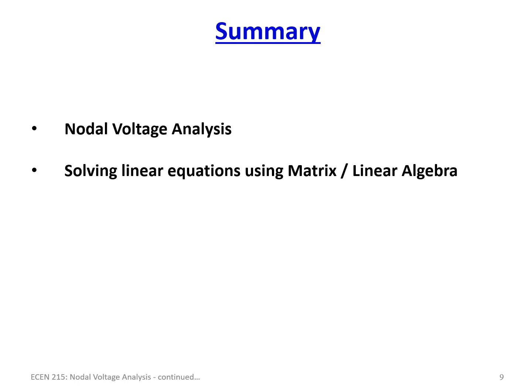I would also say always check your answers. Whatever answer you get, go back and plug back into your original nodal analysis equations, and they should equal 0 in the case of nodal analysis. The sum of the currents entering a node or leaving a node should equal 0. So KCL should be applicable in your equation. So there's always a way of checking your